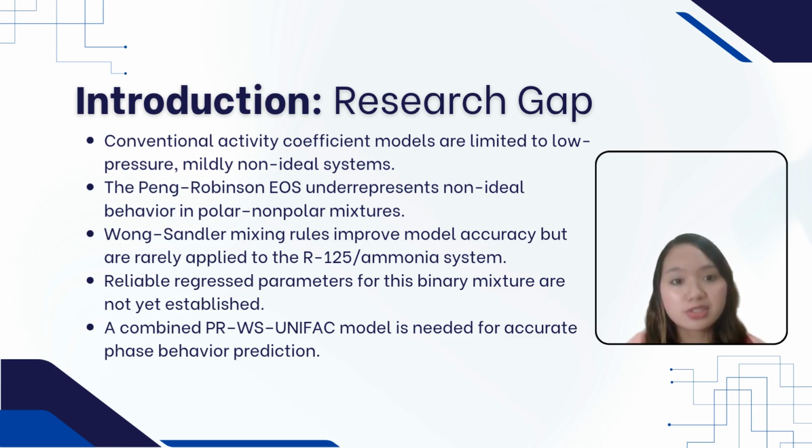Moving on to the research gap. Existing thermodynamic models have limitations when applied to systems like R125 and ammonia. Conventional activity coefficient models such as Wilson, NRTL, and UNIQUAC are effective under low pressure, mildly non-ideal conditions, but cannot accurately capture the strong non-idealities in the system. In addition, the Peng-Robinson equation of state is widely used in industry but tends to underrepresent the liquid phase non-idealities